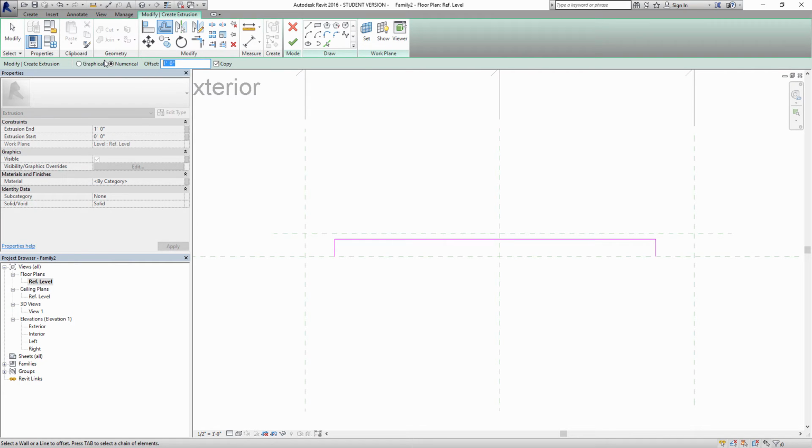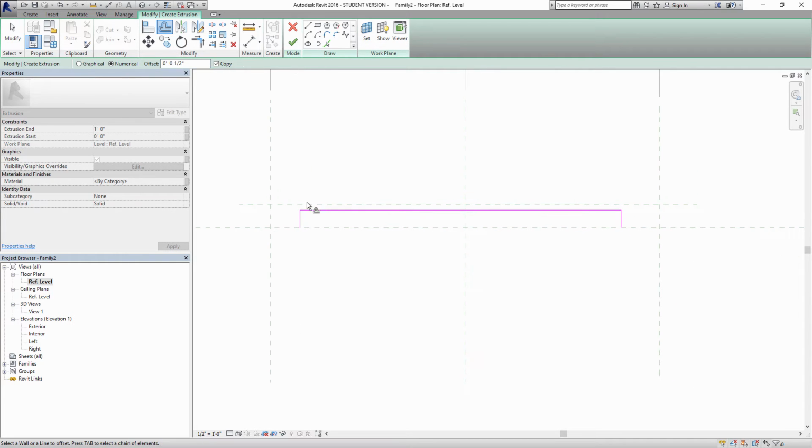And I'm going to say that my panel is a 1/2 inch thick. So I'll type using offset. I'm going to say I want to offset 1/2 inch. If I hover over my lines here, I can hit Tab and offset all of them 1/2 inch. And then I will come in and just close off the sides there.